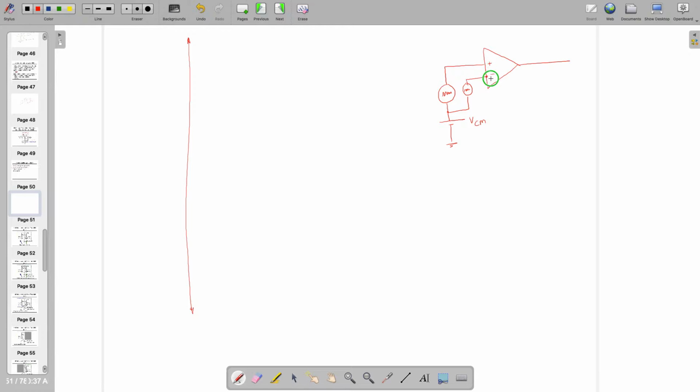This is given to plus and minus, and this is minus plus, this is plus minus, this is Vin. Notably, they are 180-degree phase shifted. These two are 180-degree phase shifted, and that's why this becomes Vin and this becomes minus Vin, and this is common mode voltage.